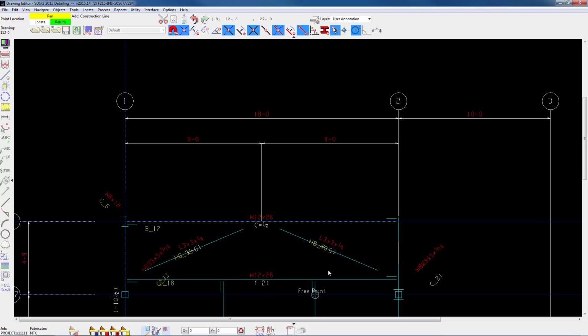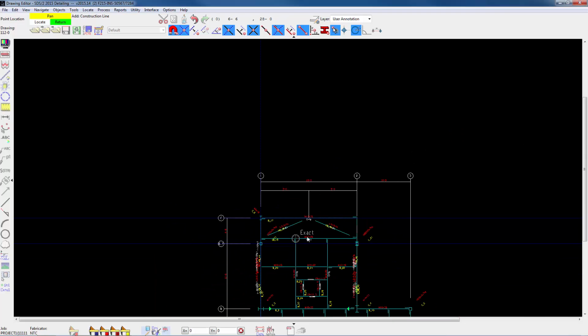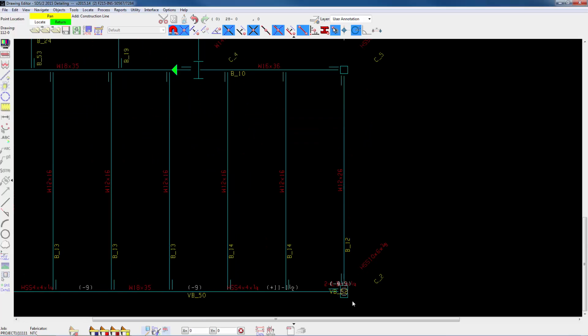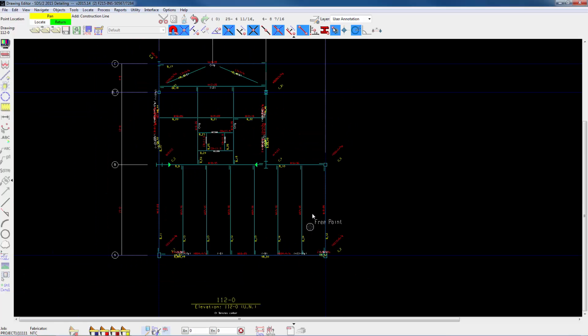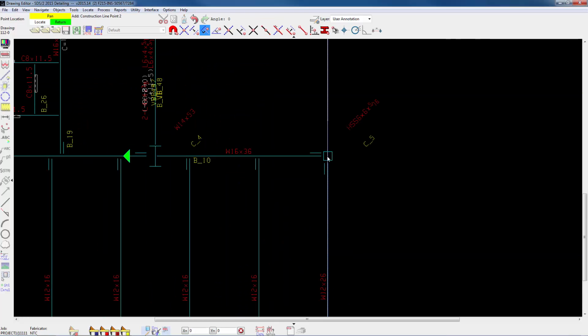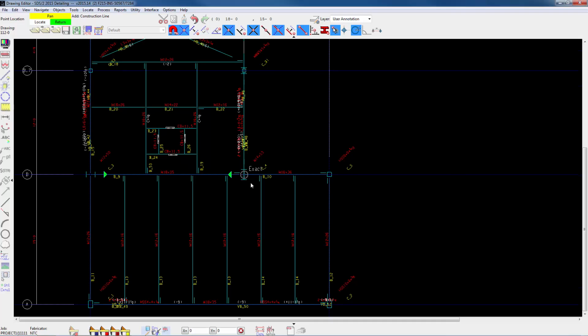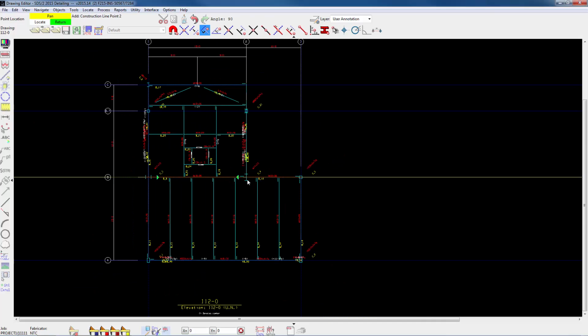And then after you do one of these, you can save that grid system and insert it into your other drawing. So again, it's my preference. I don't prefer the way the automatic detailing works of the erection views as far as the setbacks and all that stuff.